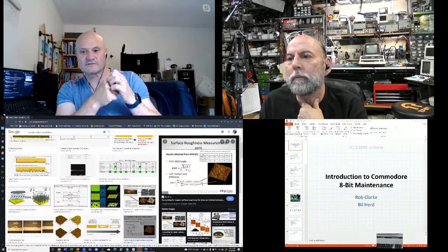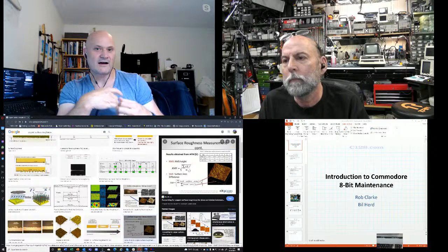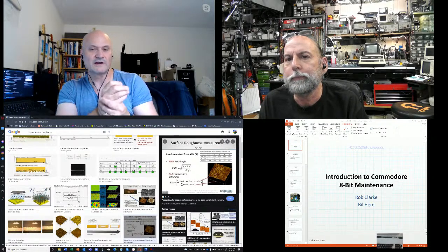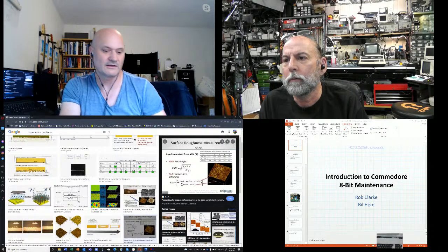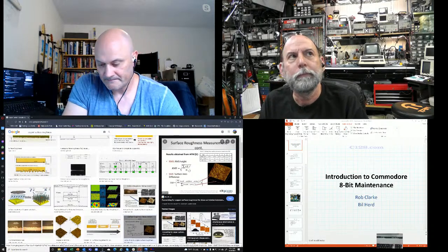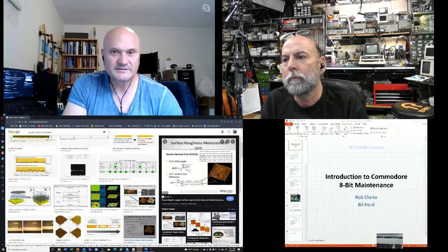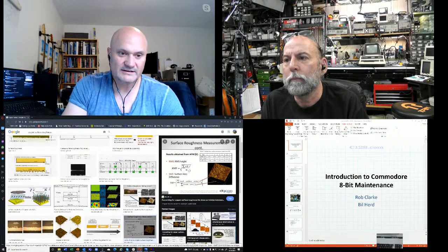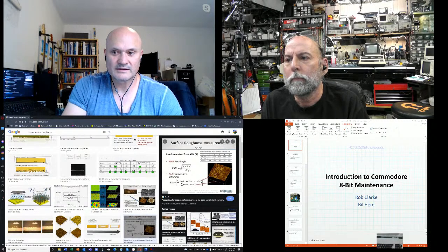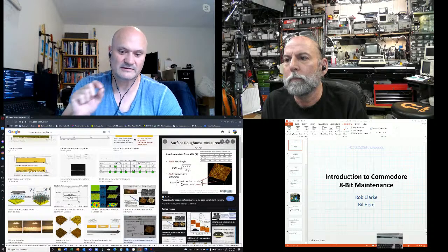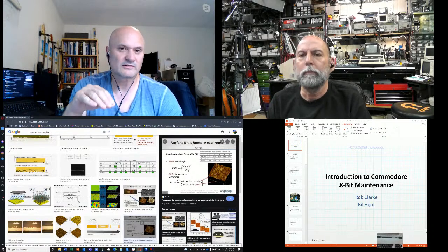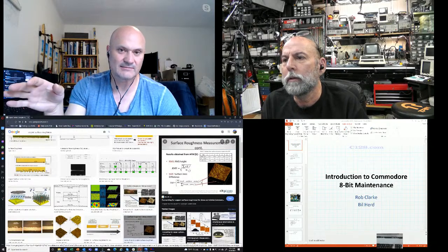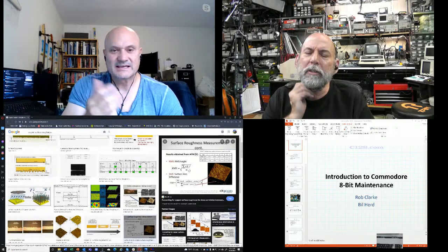So if you're doing high-powered RF boards or microwave boards or sonar, if you're doing LiDAR, or really high-speed digital, like over 20 gigabits a second, you really need to consider using different copper foils that are specially made with lower surface roughness, and so you get lower losses due to skin depth. It's called the skin effect.